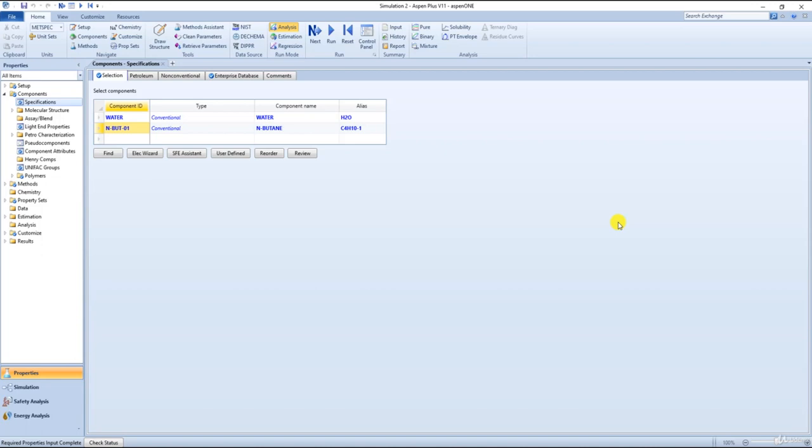As you will see further ahead in this course, a given property method may fail to end up with realistic or reasonable results. In fact, it may not even converge to give a solution. For this reason, the built-in property method selection assistant will narrow the search circle for you in order to try alternative property methods when the first suggested or default method failed to give reasonable results. Of course, it is intuitively assumed here that you have properly entered the flow rates, their components, their operating conditions, and any other physical, chemical, or thermodynamic constraint imposed for the process you want to model.